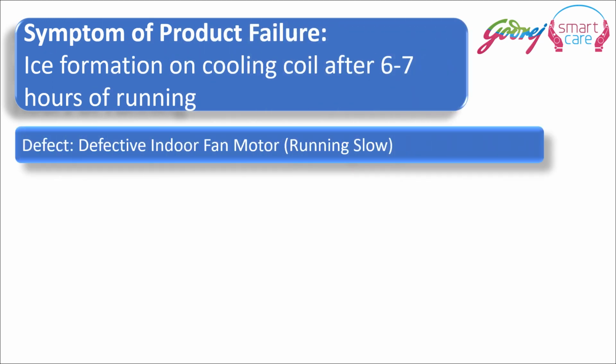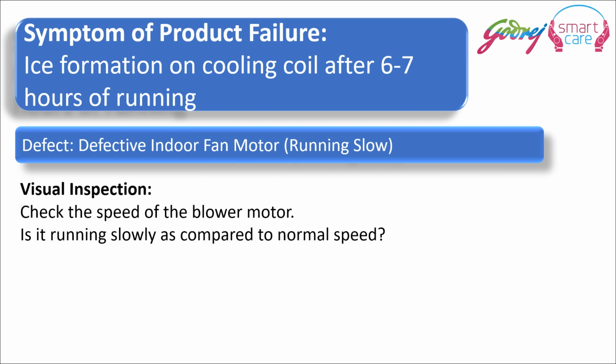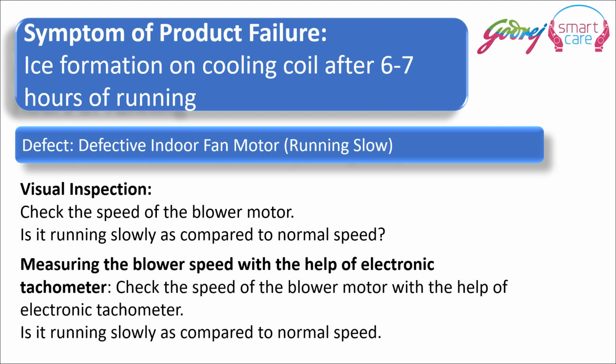Defective indoor fan motor is related to the running speed of the indoor fan motor. Visually inspect and check the speed of the blower motor. Is it running slowly as compared to the normal speed? Measure the blower speed with the help of an electronic tachometer. Is it running slowly as compared to the normal speed?